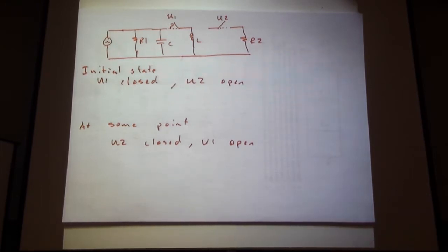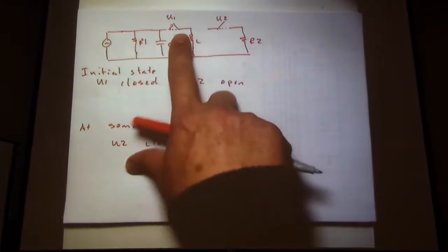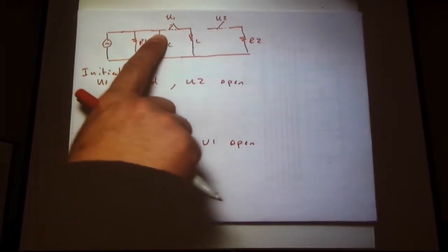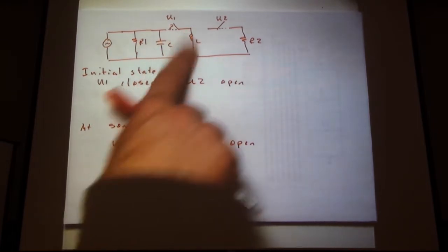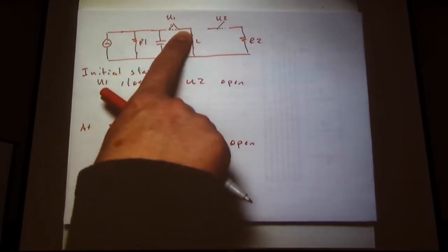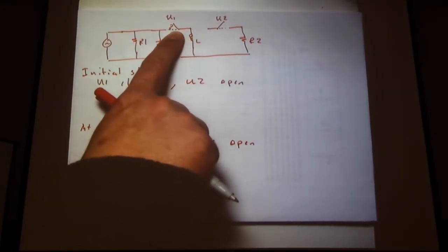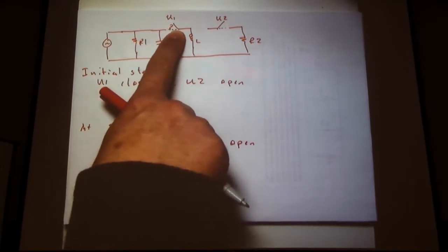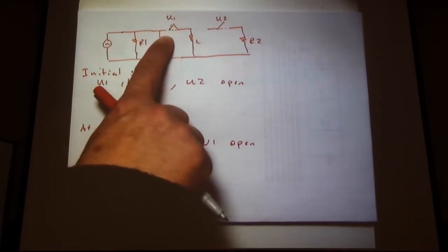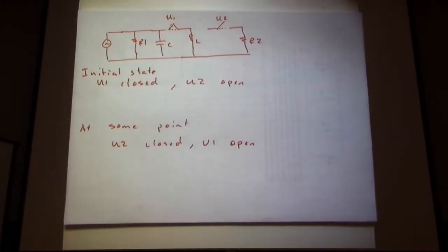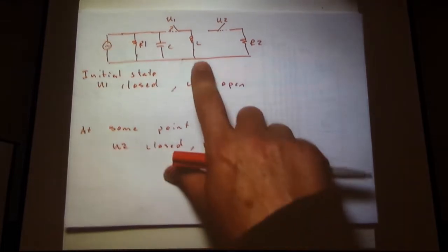If this was a real power problem, with tens or hundreds of amps through this circuit, you couldn't physically pull this open by yourself. You need a hydraulic press or something like that. The magnetic field tries to keep it closed, and you're not physically strong enough to open it yourself. That's the inductor fighting against you.